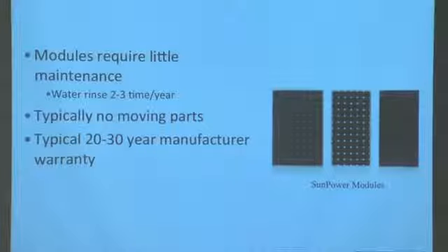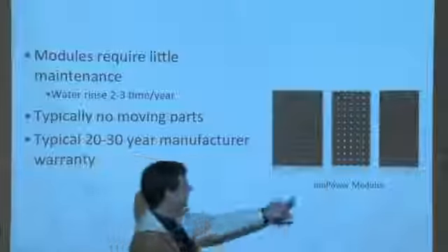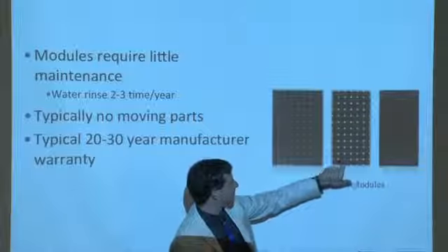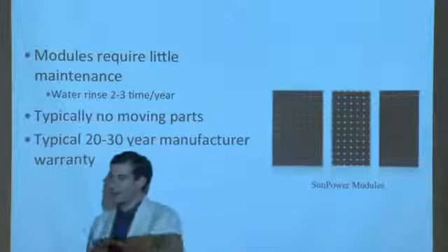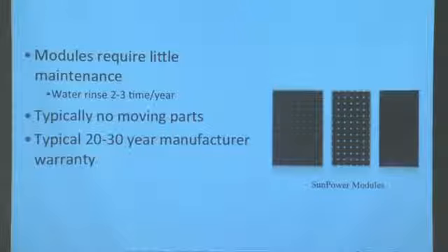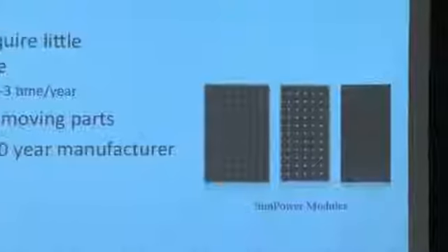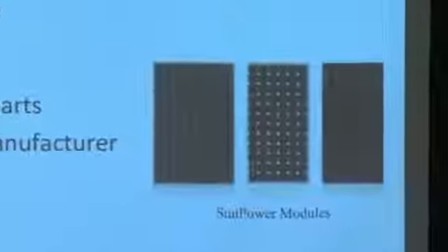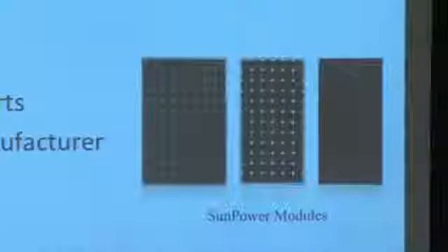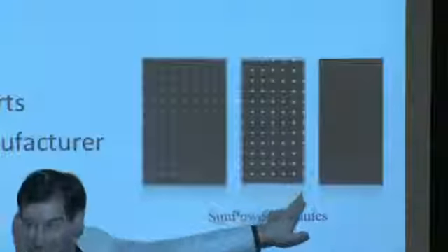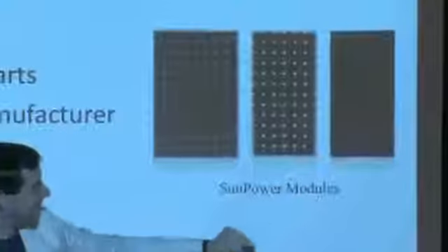We know from the lecture on crystalline silicon PV that when you see these little gaps in between the cells, those are pseudo-squares. Those are those round ingots of Czochralski silicon that have been sliced into wafers, and then the edges have been shaved off, and you have that stop sign type pattern of a solar cell. So that way you know, okay, these are single crystalline cells lined up in a module together.